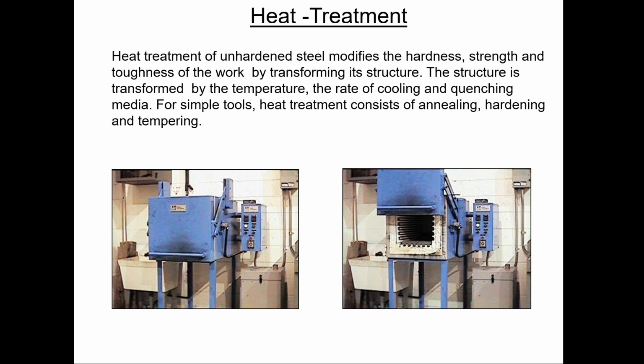I always used to keep one oven running in a tool steel shop at about 550 degrees. And that was going to be a pretty handy oven. And if it's a small enough part, I put a piece of heavy plate, like 1-inch thick plate, underneath it, and preheat everything together. If I'm preheating everything together, then when I pull it out, it's not going to go cold fast sitting on a cool bench. So I always put it on something that helps support the heat that's in it so I can do my weld process.